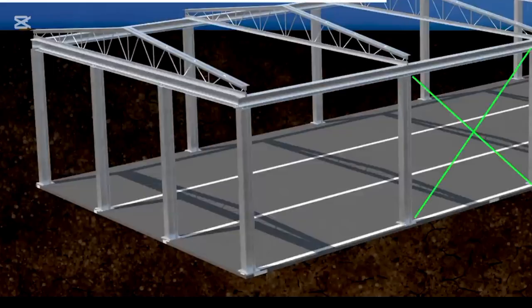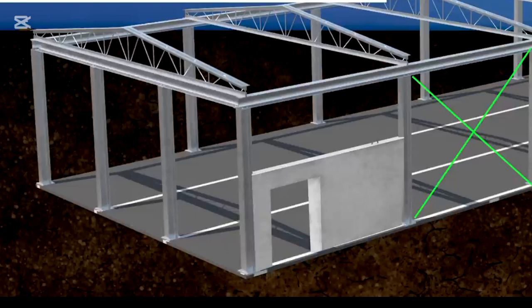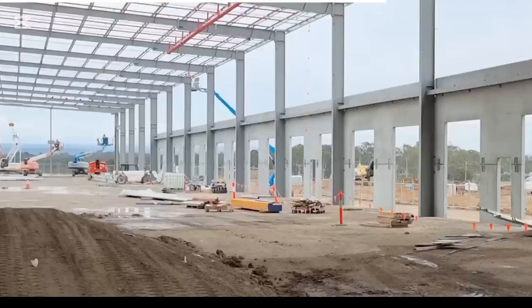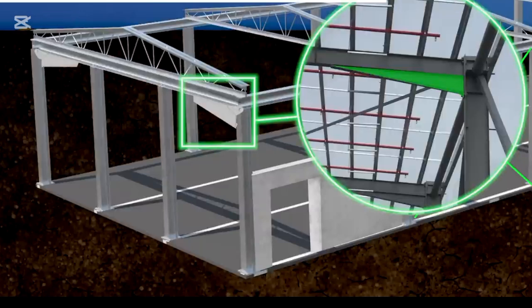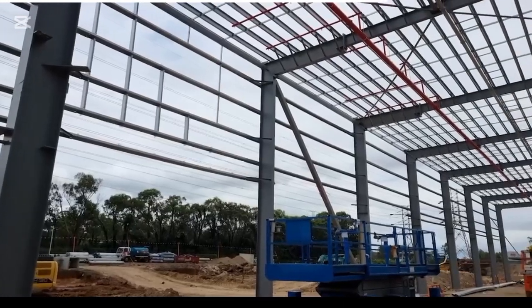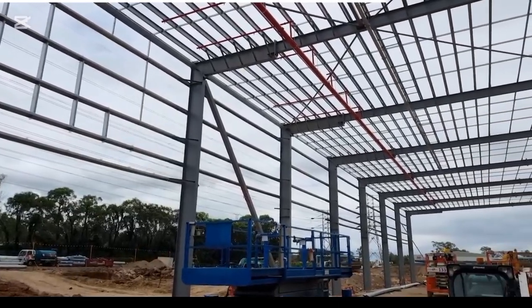Note that bracing is not the only way to make a steel structure resistant against lateral loads. For example, rigid precast panels in between columns can be used to do the same job. You can see the example here. Another alternative solution to resist lateral loads in a steel frame is to detail rigid connections between beams and columns. This approach increases the frame's stiffness against lateral movement and provides resistance to lateral loads. These frames, known as portal frames, offer the main advantage of providing an open space.